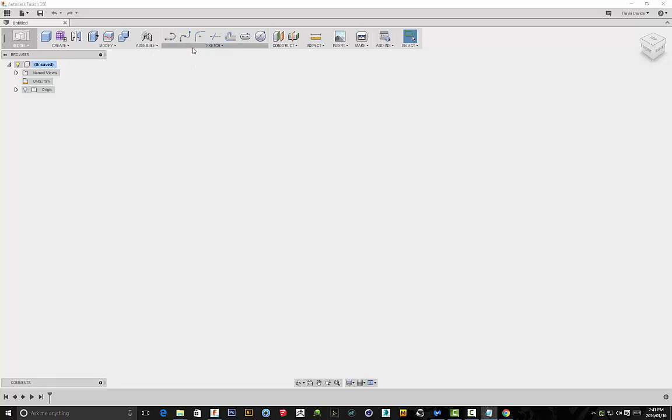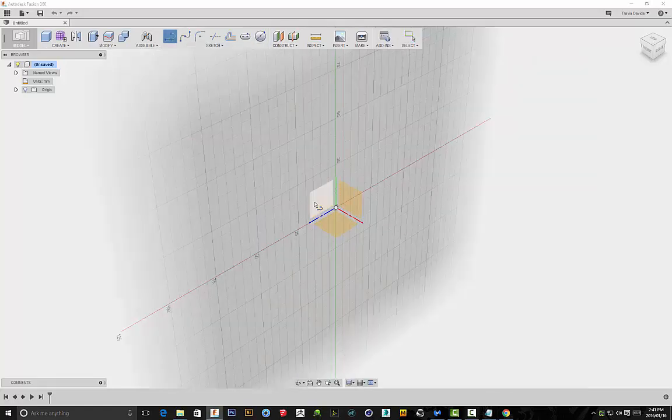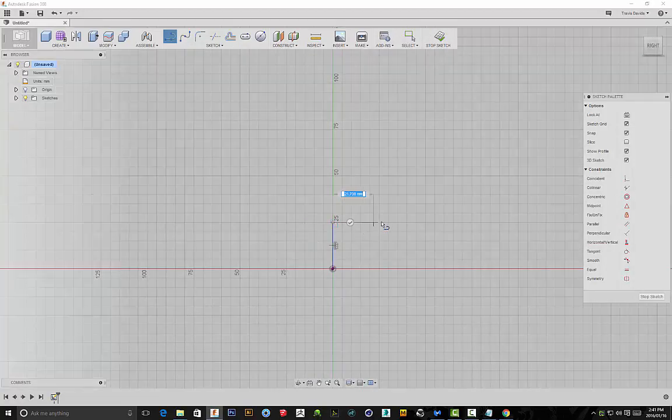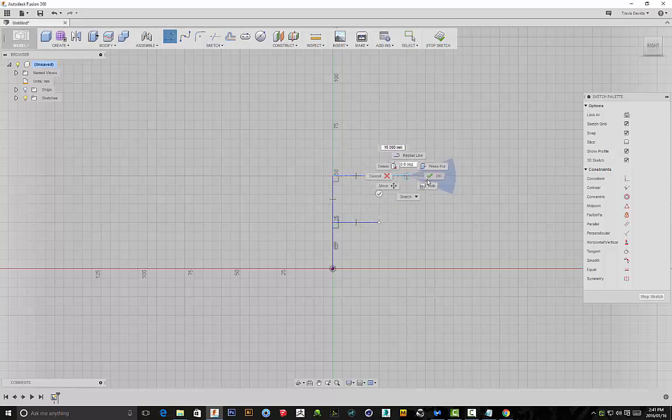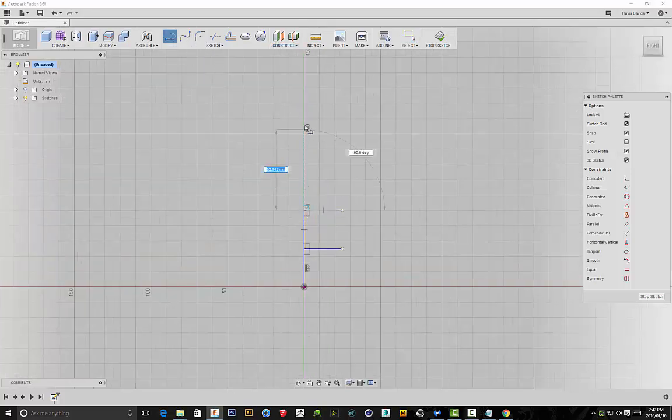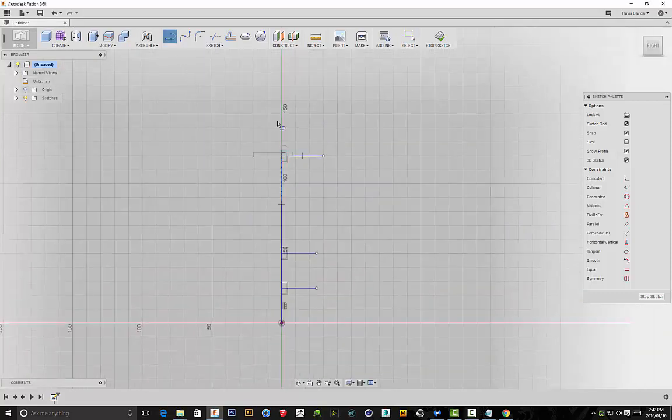So I'm going to go into the sketch function, I'm going to select line, I'm going to select this plane, and now we're basically just going to be creating different levels, because on each of these levels that we're creating here, we're going to be creating a plane at an angle. You'll see it'll be construct plane at an angle. So I'm just going to create some different levels here at different heights. So let's go with 4 levels for now.